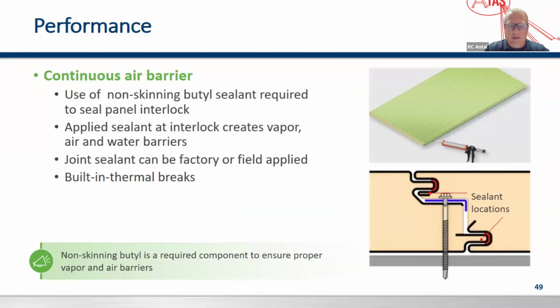But these joints would be typically tightly flushed together, making insulation to insulation contact. The vapor and air barriers are built in there, which would prevent any type of moisture into the building. But these panels would be flush, so the insulation would be touching. And you can see, if you look closely, the facer skins and the liner skins never touch. So all the panels are thermally broken, which is going to allow for that continuous insulation and also limit the amount of transfer that we would have.